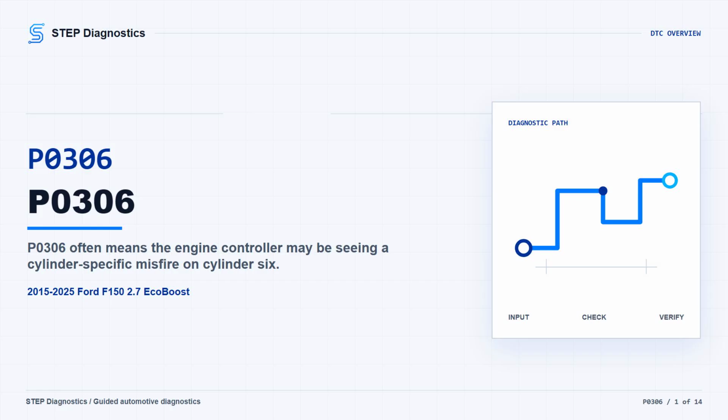The fault area may be ignition, fuel delivery, base engine condition, vacuum or EVAP leakage, EGR behavior, sensor input, or an intermittent crank signal issue. If the MIL is blinking once per second, treat it as a catalyst risk misfire. Also remember that startup misfire information may involve the first 1,000 revolution test interval following engine start, so captured conditions matter. Before clearing codes, record the freeze frame information, because clearing PCM DTCs erases that captured data.